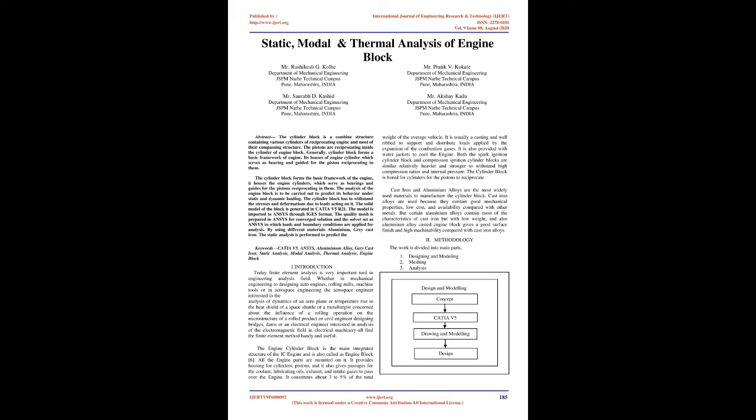The analysis of the engine block is to be carried out to predict its behavior under static and dynamic loading. The cylinder block has to withstand the stresses and deformations due to loads acting on it. The solid model of the block is generated in CATIA V5 R21. The model is imported to ANSYS through IGES format.